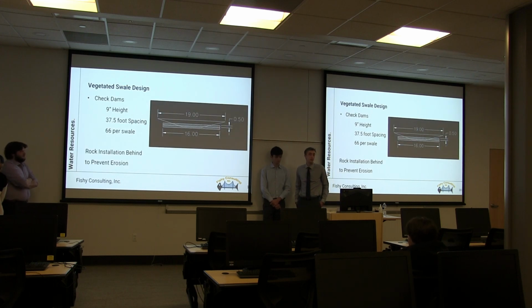Check dams will also be used within the swale to ensure that the water velocity stays below the 0.9 feet per second limit, and check dams will help to encourage infiltration and provide a water quality volume.